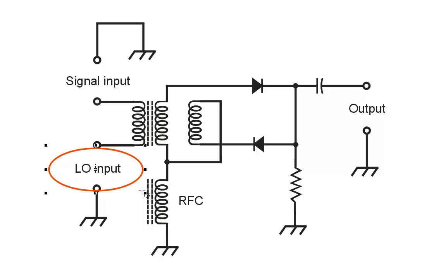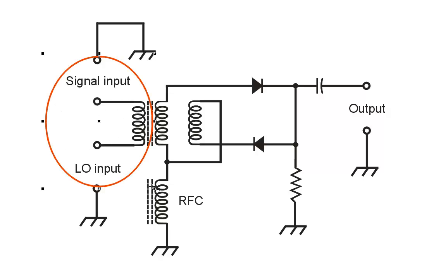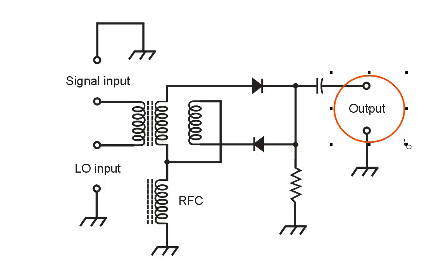It has to have the same frequency that the carrier originally had in this signal before it was turned into single sideband. Single sideband, remember, has a suppressed carrier, but that carrier frequency still exists, and this local oscillator has to be at that frequency. So what we end up doing is mixing these 2 things here to get a difference frequency, which ends up being the output, and that turns out to be audio frequency energy.